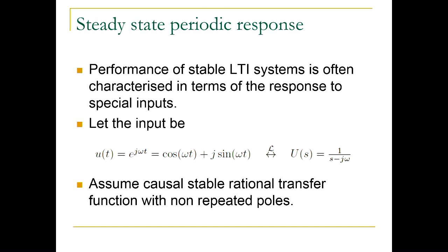All right, so when we talked about time domain specifications, we were using a special input. We were using step input as a test input to our system. And that's how we defined overshoot, rise time, settling time, and steady state errors, right? So sometimes we use ramp inputs, sometimes step inputs, etc. In all the frequency domain analysis and design tools, we will be using sinusoidal inputs. It's almost like thinking about Fourier series versus Taylor series. So now we are talking about Fourier series style questions.